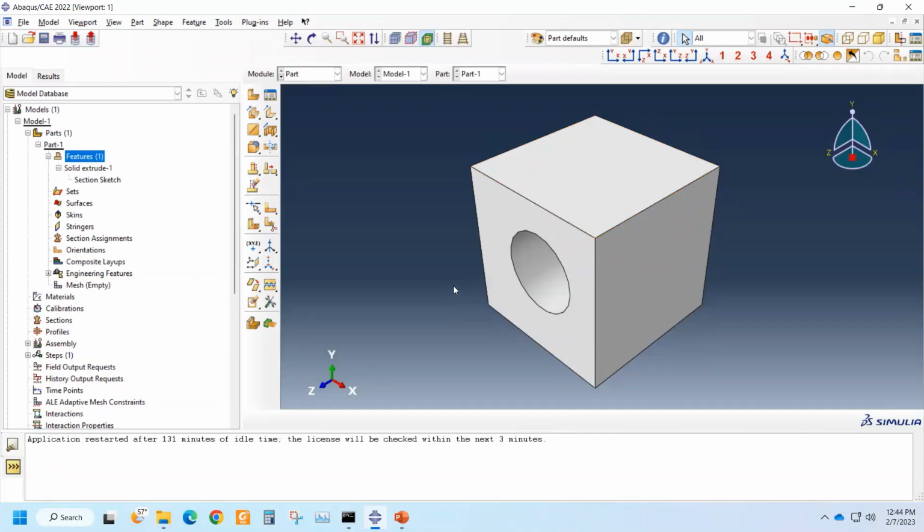So that's how we do it. But are there other methods? Yes. Sometimes you may have to use an orphan mesh. Generally, we use a geometry or import a geometry, but sometimes we don't have a geometry. We have to start with an orphan mesh. That is just a mesh, not a geometry. So we can create a geometry from the orphan mesh for our use. Also, if our existing geometry, let's say we have imported it from somewhere else, probably from some other software, is faulty as per ABAQUS definition, there are repair tools.